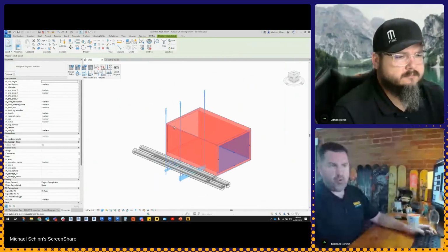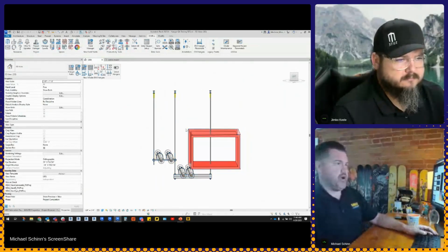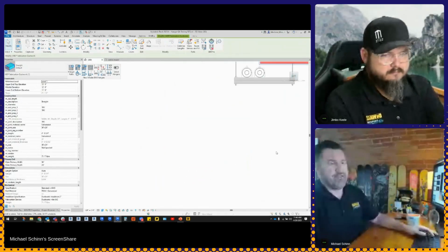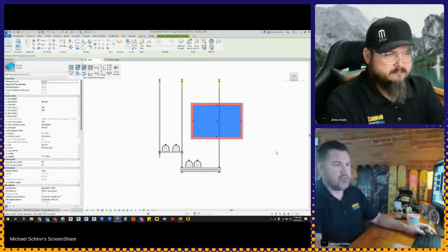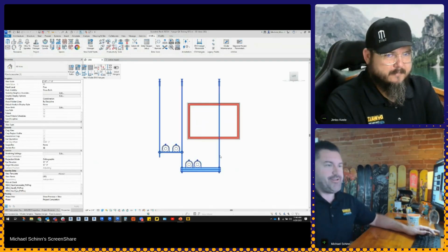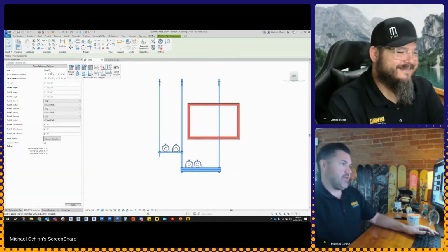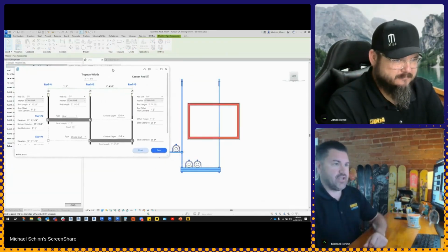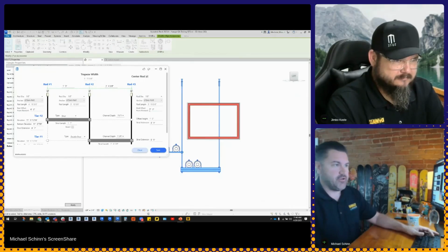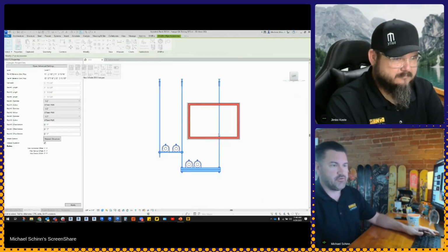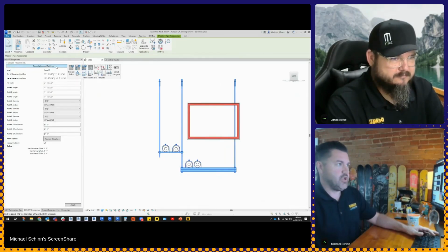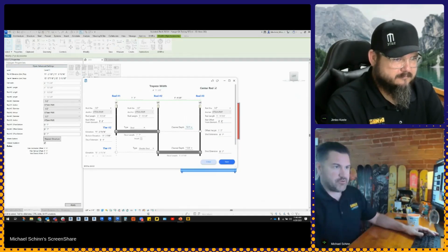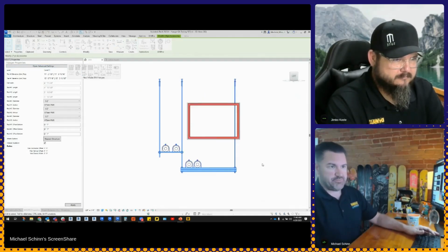So like I said earlier, I want to be able to make some kind of automatic clash detection. Man, I wish you could just do that, right? As a coordinator, just be able to move that duct out of the way. But yeah, I want to be able to click onto that hanger and adjust that. And that's where rod offset comes in. I can say, all right, let's move this over, maybe another foot over to the right. So you do have the ability to manually make your adjustments.